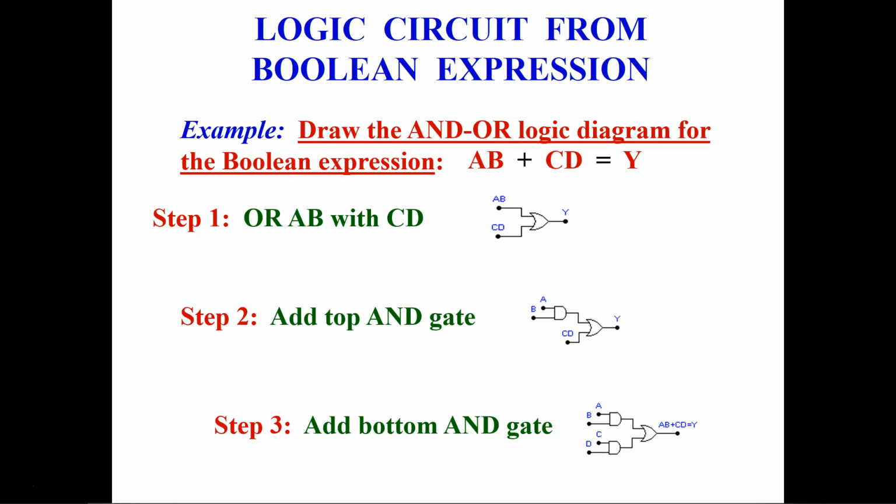So here the key takeaway is that you should make sure of what the main logic gate is that we should be using. For example, in this case, the main logic gate was the OR gate. So you first see the big picture, what is going to be the main gate, and then work backwards, seeing what gates are needed to get into it. You saw that we started with the OR gate, and then we went to the other inputs and made the AND gates.